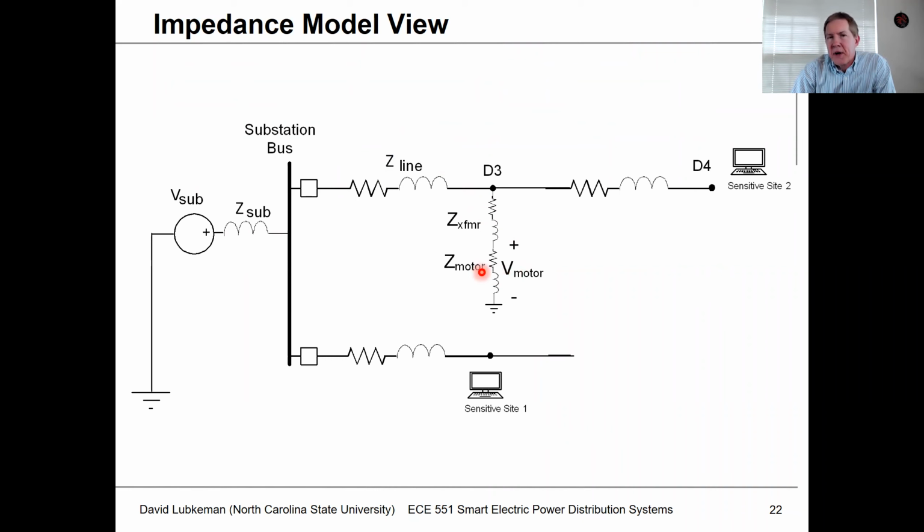And then we'll go ahead and neglect the voltage drop due to load in our hand analysis, but the WindMil program is actually going to include this. And so between D3 and D4, if we did this by hand, these voltages would essentially be the same because we're neglecting the voltage drop across here. Similarly, if I'm going to look at this side on the adjacent feeder, if I neglect the voltage drop here, we were just basically interested in getting the substation bus voltage.